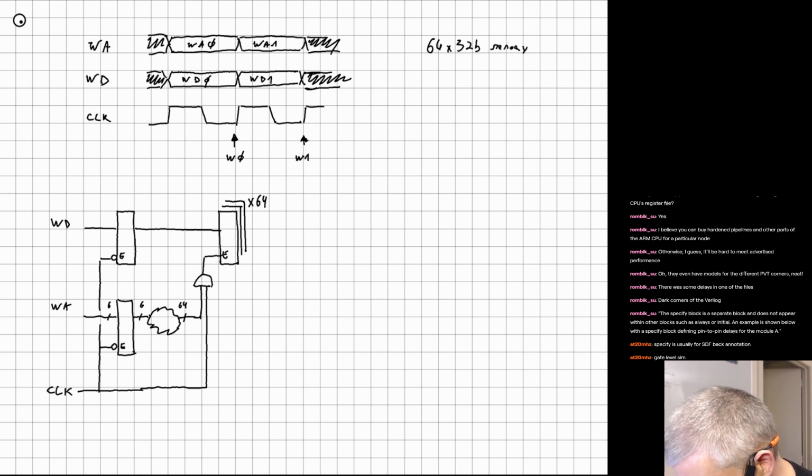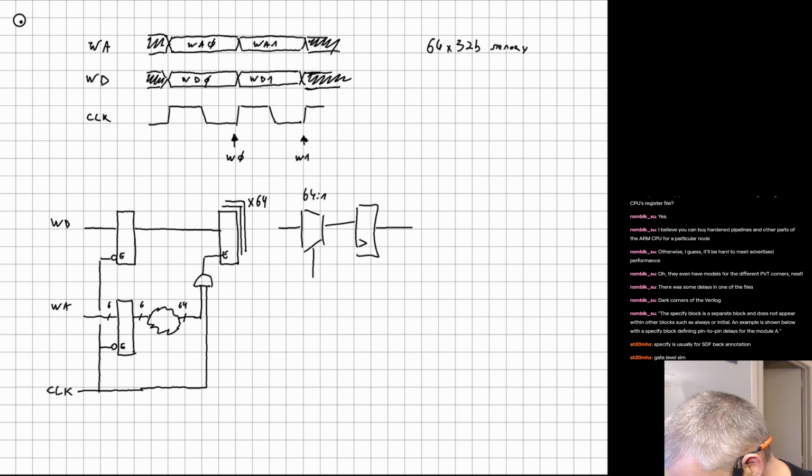So the first thing I thought was just basically take a mux and do a 64 to 1 mux, and then output registers, and there you go. And then you have your read address 0 and read data 0. Okay, that's a simple solution for a read port. The problem is the 64 to 1 mux tends to be very large and very annoying to route.